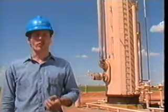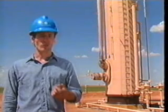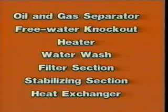The vertical heater treater is the most commonly used emulsion treater in the oil industry. Used for three-phase separation, it may include one or all of these components or sections: oil and gas separator, free water knockout, heater, water wash, filter section, stabilizing section, and heat exchanger.